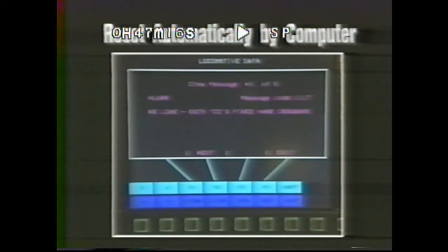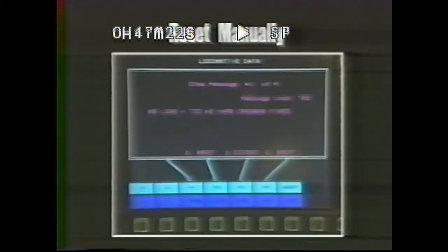Just like with ground relay protection, the locomotive will reset most crowbars automatically. But if the locomotive fires 2 or more crowbars for the same fault in a short period of time, it will drop out locomotive loading and lock out the electrical system. In this case, the crowbar will have to be manually reset using the display.